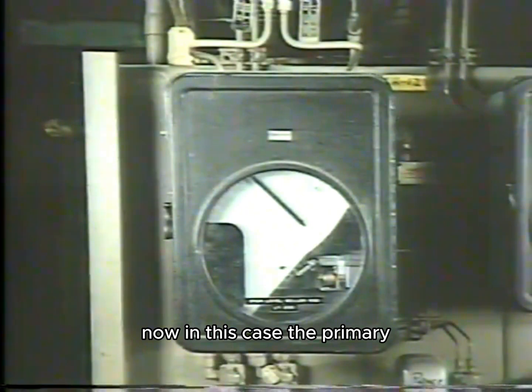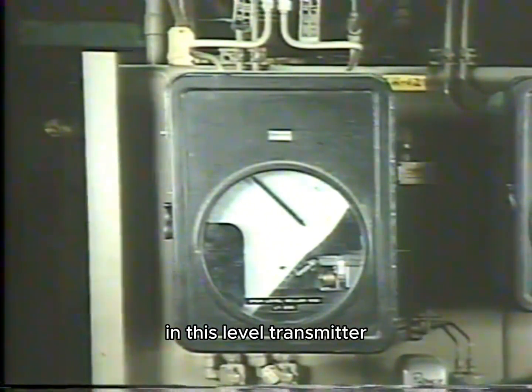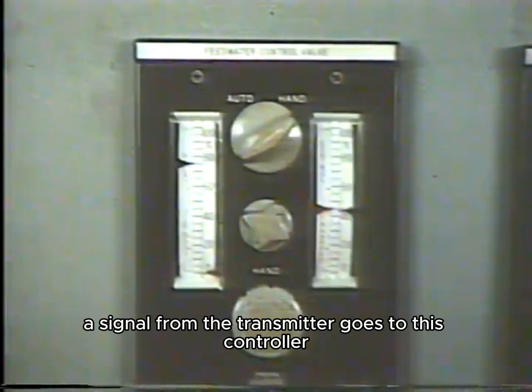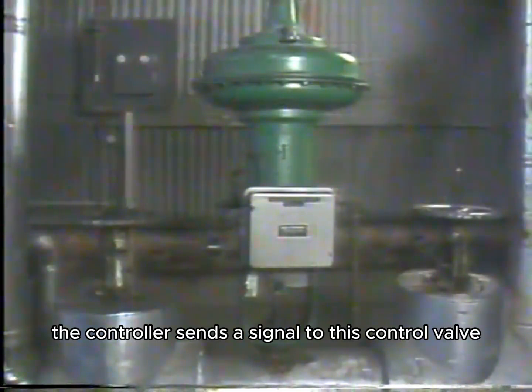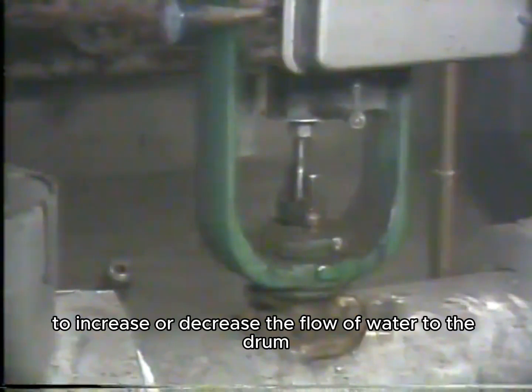Now, in this case, the primary and measuring elements of the control loop are combined in this level transmitter. We'll describe what it does a little later. A signal from the transmitter goes to this controller. The controller performs its four functions of measuring, comparing, computing, and correcting. The controller sends a signal to this control valve, which opens or closes to increase or decrease the flow of water to the drum.